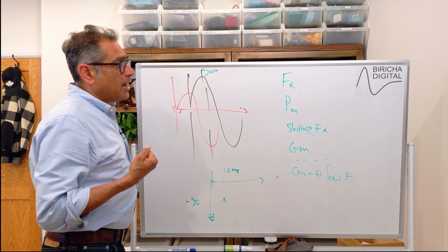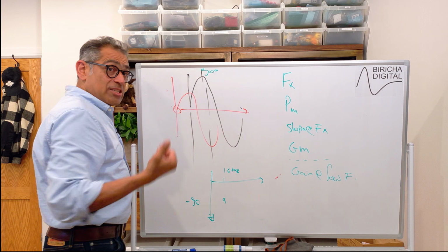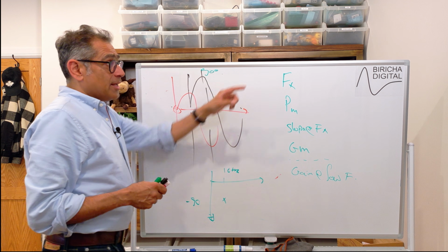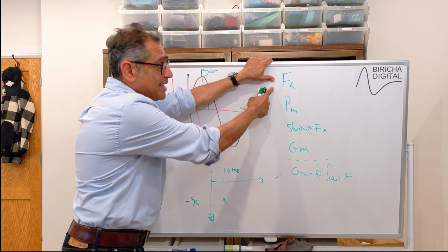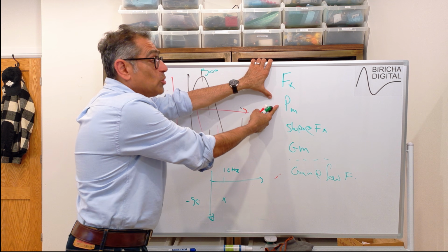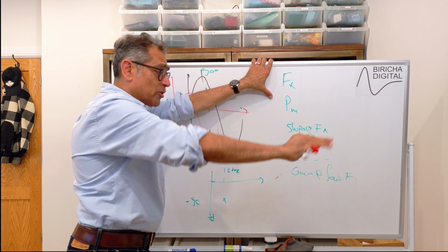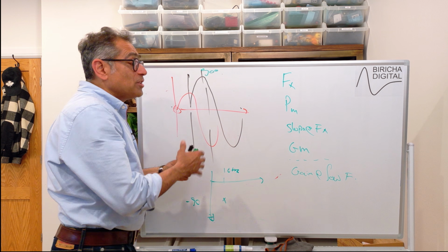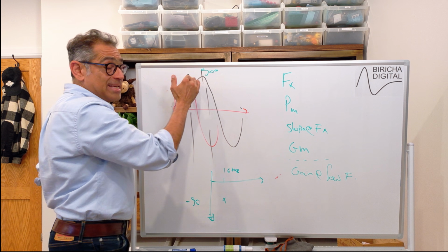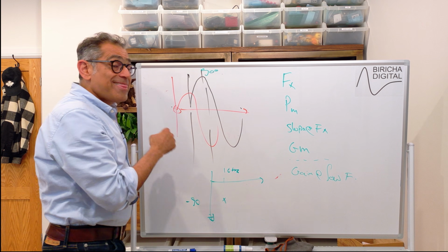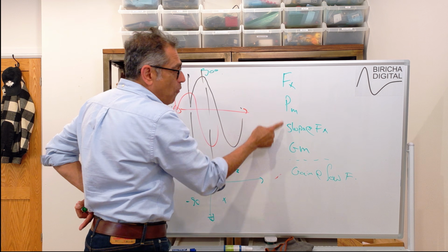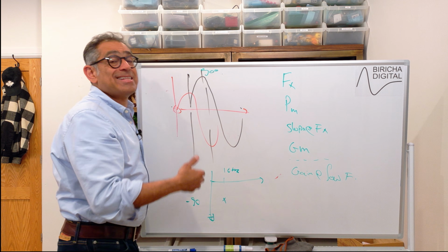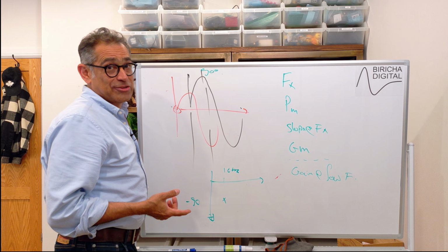Now, when I have got these 2 plots, then I only have to look at 4 points on this plot. One of them I call the crossover frequency. At another point, I'll be assessing what's called phase margin, the slope at crossover frequency, and the gain margin. Finally, this is not part of the stability, but I want to have a high gain, a high dB at lower frequencies. And that's it. So if I look at these four, for my stability, and this is actually for good regulation, I can assess the overall performance and in particular the stability of my power supply.